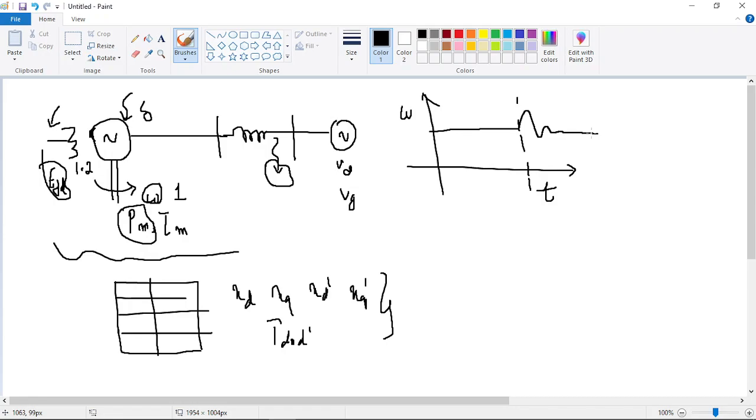If the system is stable, it will oscillate for some time and reach some steady state point after the disturbance is removed, or another steady state point is reached; in overall language, the system will be stable. But if the case is unstable, then the system will lose synchronism, and something bad happens here. I think you have understood the initial condition.